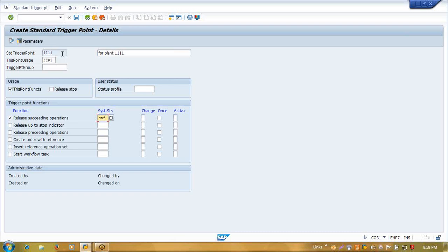Suppose you have one block of metal, and in that metal block you want a tap, you want to do some kind of threading. So your first operation will be the sizing of the block, second operation will be drilling, and after the drilling you can do tapping, the threading part. So we can create two operations. First is drilling, second is tapping, but tapping cannot be done prior to drilling.